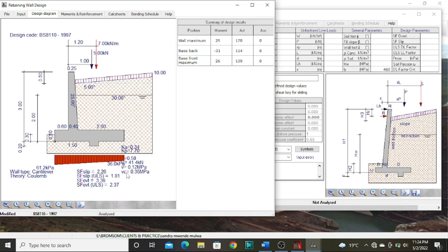And then from observation, you can observe V is equal to 41.8 kilonewtons. And then the active and passive earth pressures are also given. These are the coefficients. The angle of internal friction, 25 degrees, is here. And this was 5 degrees, the angle of inclination of the soil with respect to the wall. And these values that you also had inputted at this section are also given here.